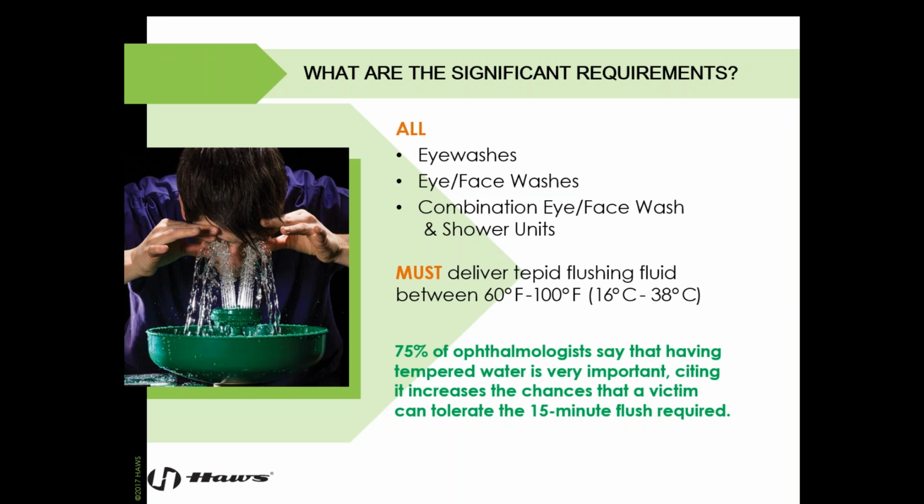So you can't receive your emergency shower and eyewash combination unit and say, I'm ANSI compliant. It needs to be installed. It needs to be tested to the full ANSI standard to ensure compliance. So we've done some studies, 75% of ophthalmologists say that having tempered water is extremely important, saying that it increases the chance of a victim to tolerate the full 15-minute flush.